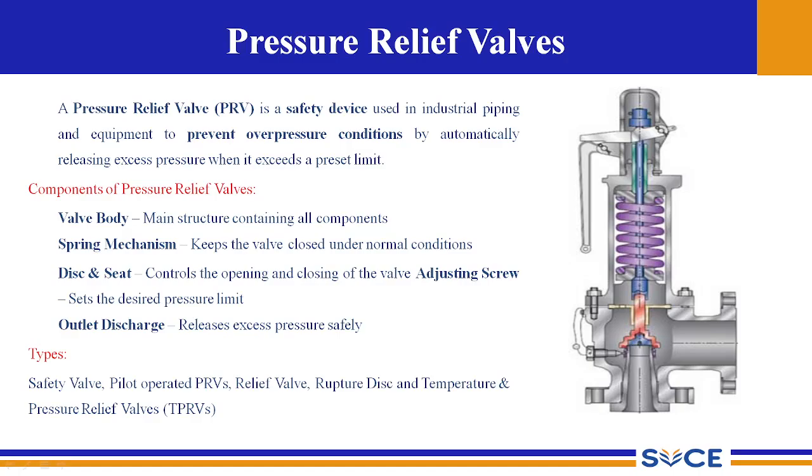The screw will actually set the desired pressure limit. Once the desired pressure is exceeded, the valve actually opens, and the excess pressure is let out.